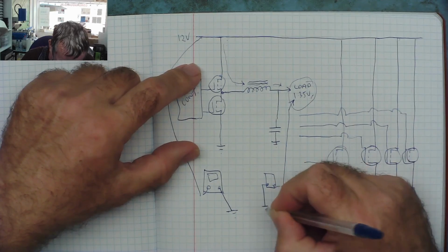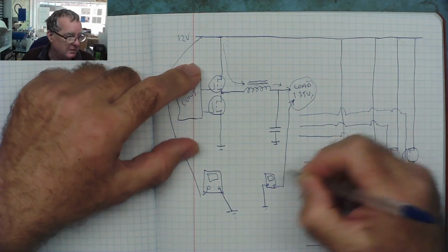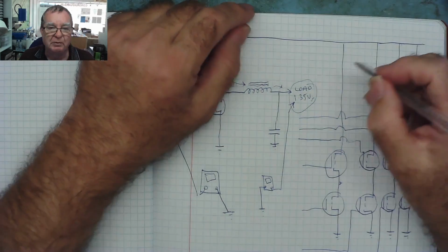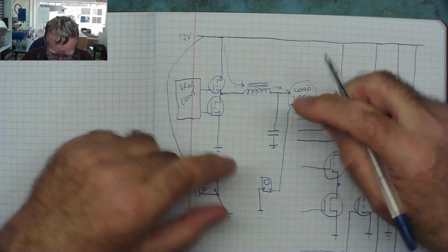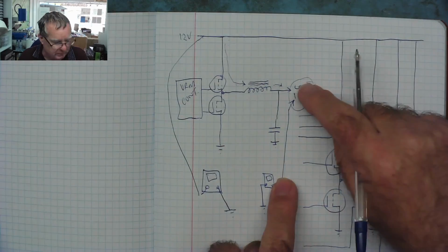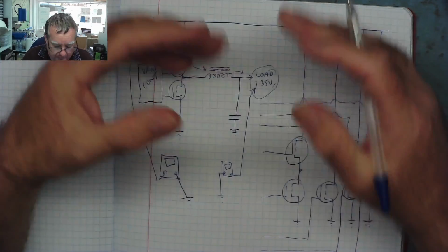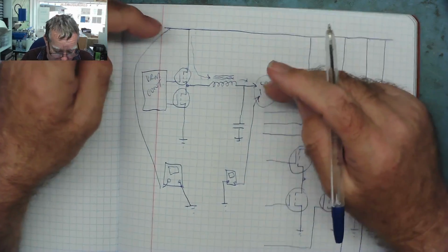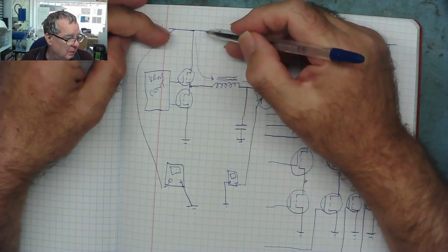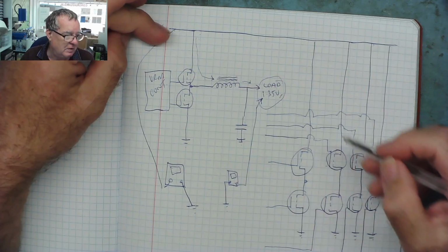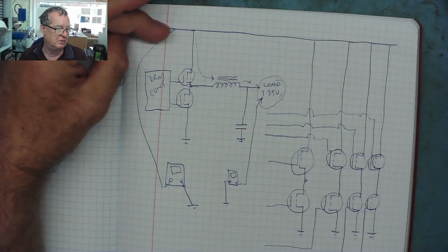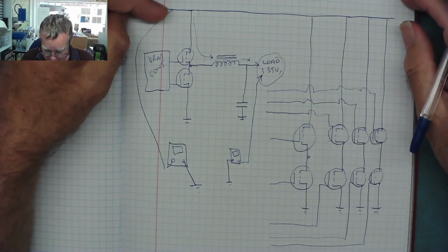I've drawn the meter backwards, but some guys, I know, will actually use their digital multimeters backwards, red and black wires. So measuring here is the same as measuring here. This is why the resistance you see from the 12 volts to ground will match the resistance of whichever VRM has the shorted MOSFET.